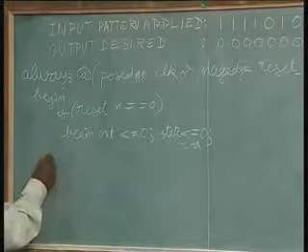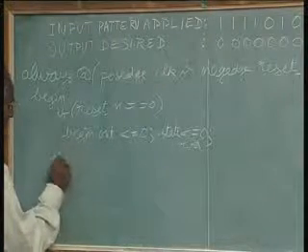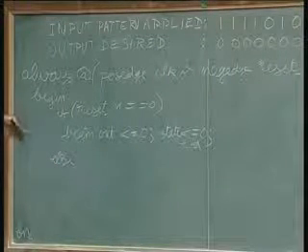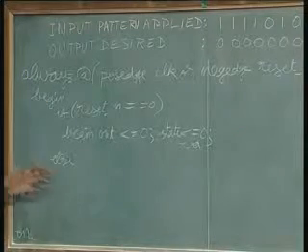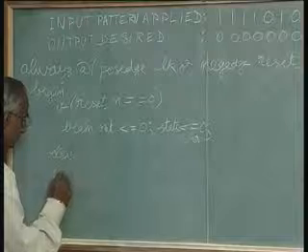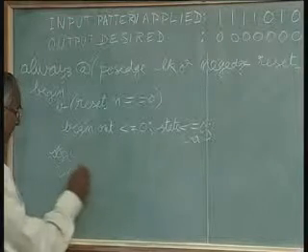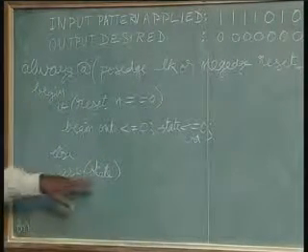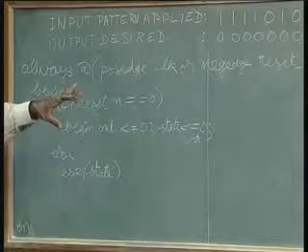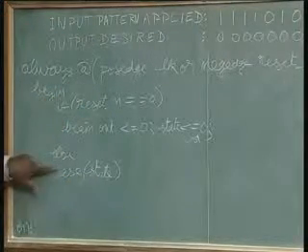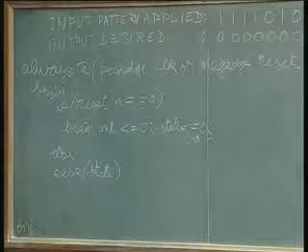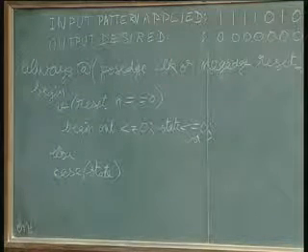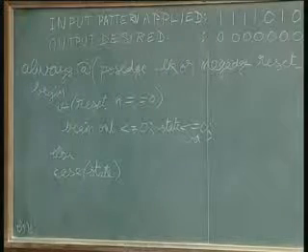So if not, that is else, what we should do is keep on accounting for each of the states. There are just 4 states, so we will use a case statement here. And the case depends upon the actual state here, right? The state is only a decimal number for ease of writing. Note that this is not a capital C but ordinary c, because Verilog is case sensitive, so you have to take care of the case. Whereas VHDL is not case sensitive, right? That's the difference between VHDL and Verilog.